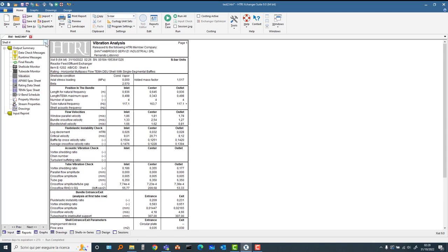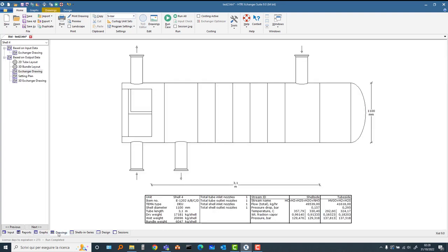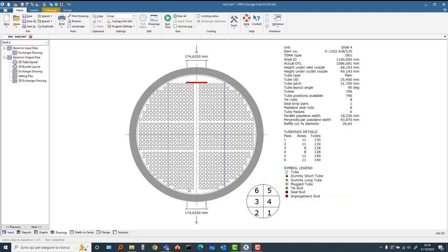One more note, let's look again at this tube sheet layout. Tube layout, 2D tube layout. Note that with the vertical cut there is also a further advantage. It is to avoid the possible bypass through this large lane, which is due to the bend radius of the inner tube rows.